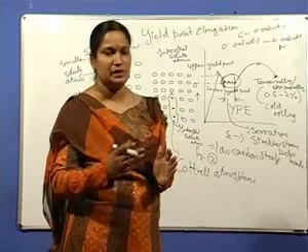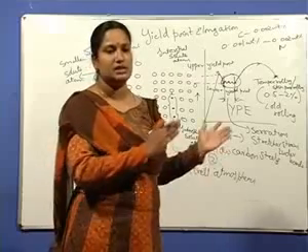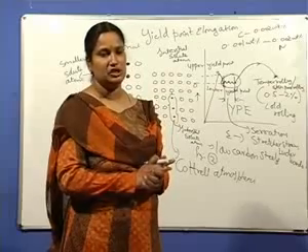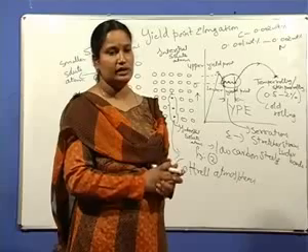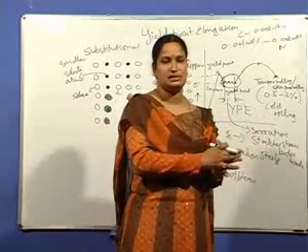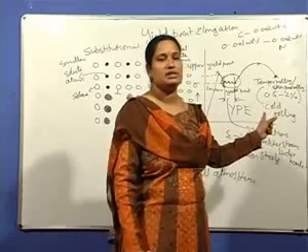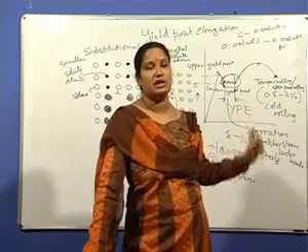The sheet forming has to be carried out as immediately as possible after temper rolling or skin pass rolling, to avoid this yield point elongation. If the material is left over for a few days, and then formed, reappearance of yield point elongation or yield point phenomena takes place.